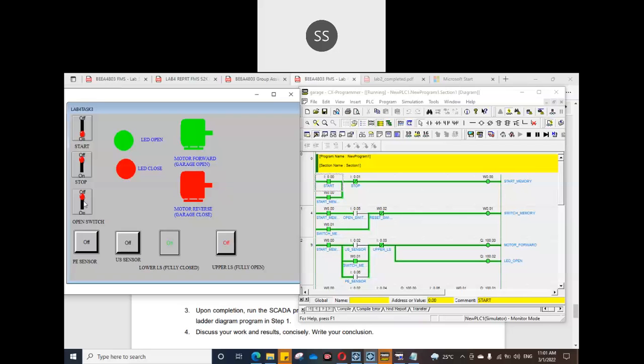Okay, so you can see the motor is forward, so the garage door is opening. The lower limit switch is not in contact, so the lower limit switch is off. It will go until the upper limit switch hits, so the motor is stopped.